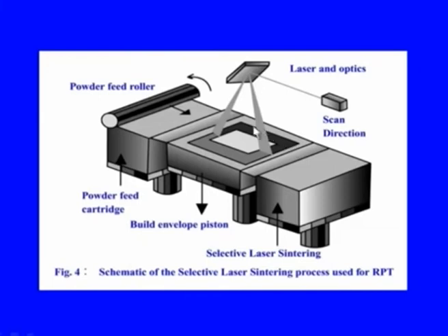However, in the next iteration, probably a different geometry can be scanned and produced. That is why it is called the selective laser sintering process. Selectively we can melt the powder particles and form the solid out of this.